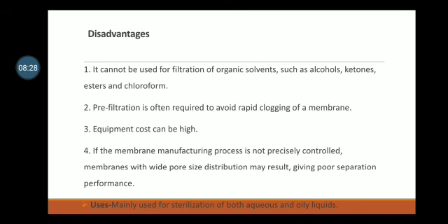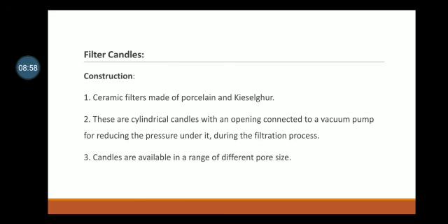Disadvantages: it cannot be used for filtration of organic solvents such as alcohols, ketones, esters and chloroform. Pre-filtration is often required to avoid rapid clogging of the membrane. Equipment cost can be high. If the membrane manufacturing process is not precisely controlled, membranes with wide pore size distribution may result, giving poor separation performance. Uses: mainly used for sterilization of both aqueous and oily liquids.